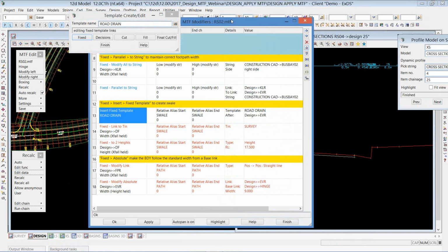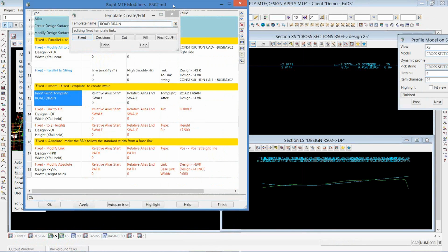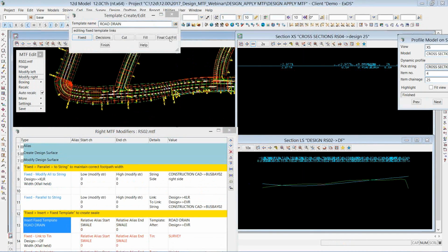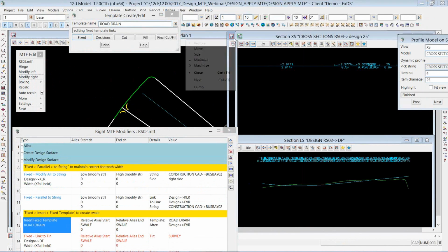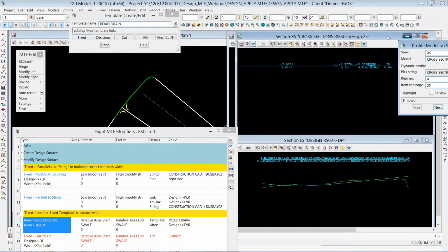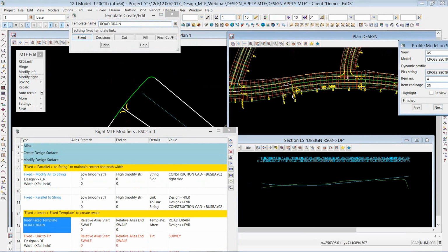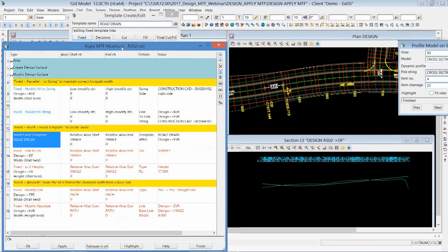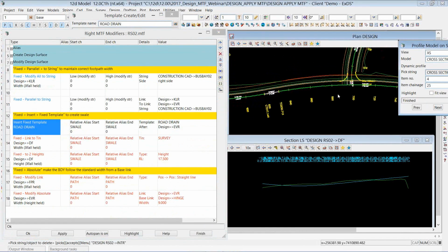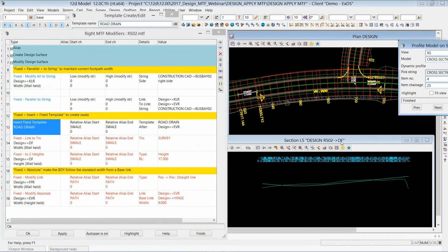Bring up a long section view, and you'll see here, just try and position the view so we can see everything. Bring that onto the front. Here we go. So I can keep recalculating and show you this pretty cool command in here. So I've got that one in there. Now you'll notice that this front of the drain there, in terms of the swale that I put in, you can see that's the grey that it's got currently produced off the road design, because it is actually just mirroring the road design. I'm not doing anything else. It's basically that's the longitudinal grade of the road.